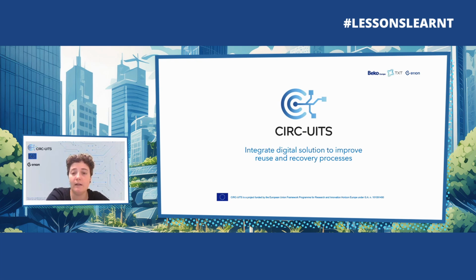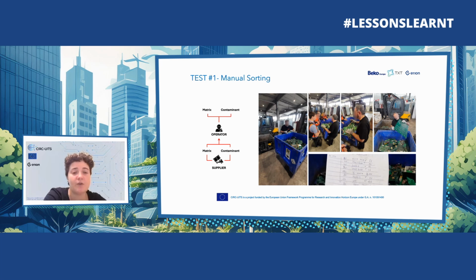Basically, we've been learning from the treatment plant the strategy for the sorting. They explained to us which parameters are behind it. For example, whether you can see the gold with your eyes on the board or not, or whether there are some ceramic components on the board. All of these parameters allow them to have an almost clear distinction of which PCB should go under which flow: the very high value, the high value, and the middle value.